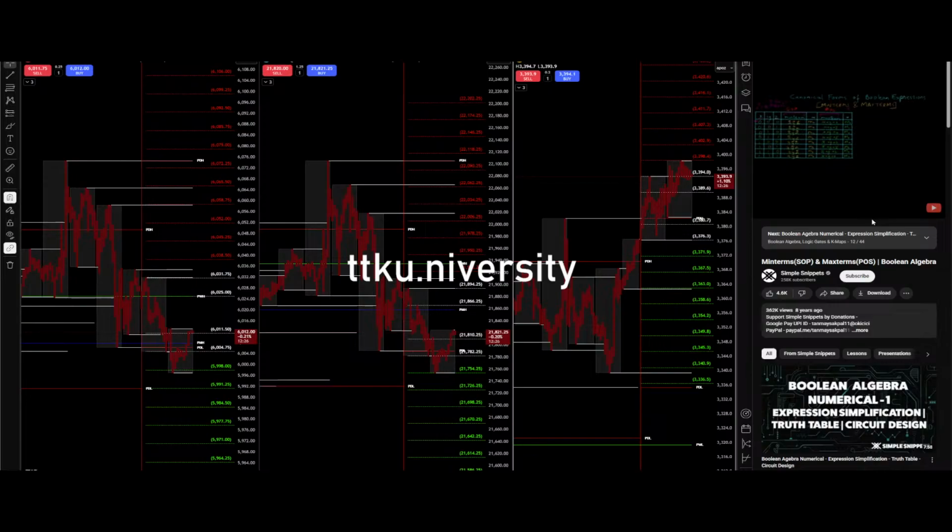Now min terms are denoted by small m and their position. That is, these are the values at position 0, or you can consider this the 0th row. So that is the reason why we say there is m0, and the associated x, y, z variables have values 0, 0, 0. Similarly, max terms are denoted by capital M with their corresponding value, that is 0 in this case, since at the 0th position we have all the x, y, z values as 0.